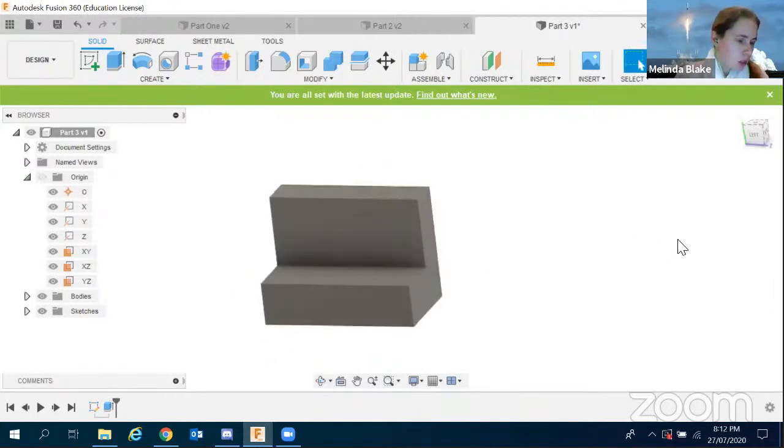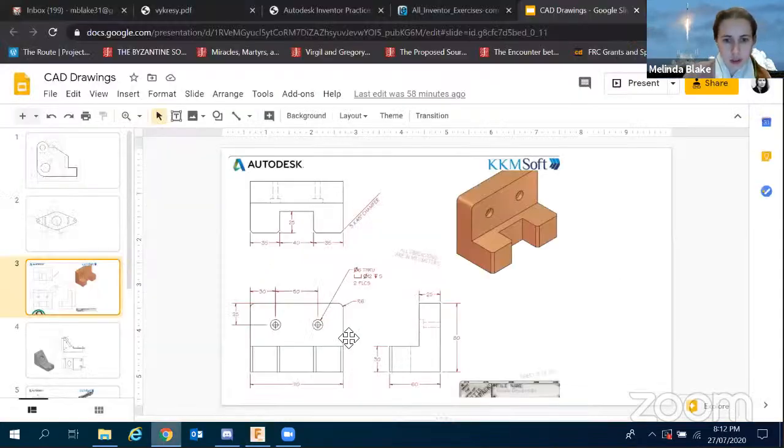Okay, so that's the basic shape. I'm now going to start thinking about adding in some of the other features. So if I go back over to the sketch, you can see from a top-down view, there's this big cutout here in the center. Now, I'm overlooking all of these angled cutoffs, all of these chamfers, because there's a tool for that I can use right at the end.